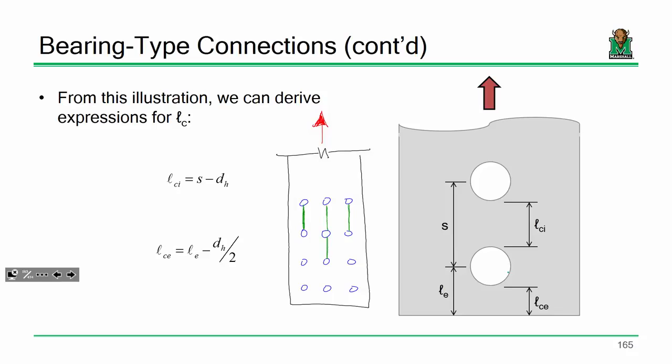So real quick, let's just make sure we're clear on this. How many interior bolts does this connection have? 9. And how many edge bolts? 3. Okay? So everybody okay with that? All right, we're going to do an example here in a little bit, and that'll actually matter when we look at bolt bearing. Yes, sir.